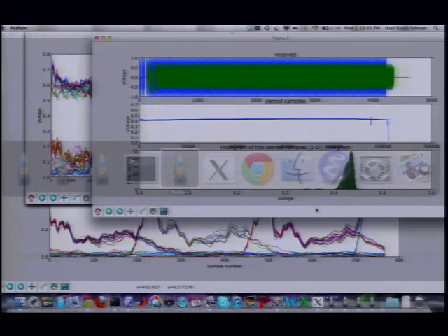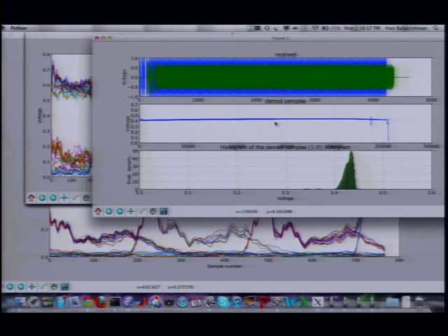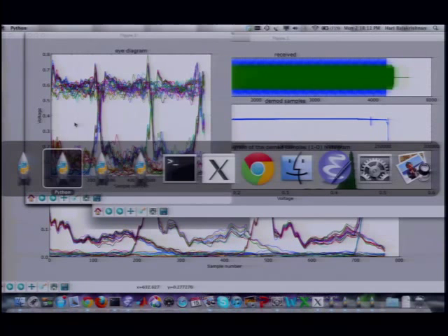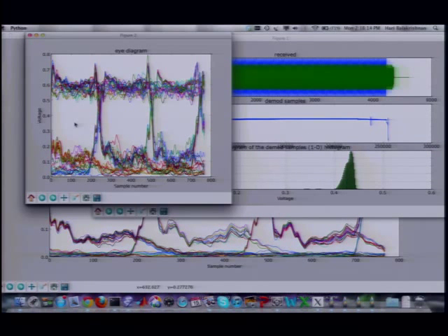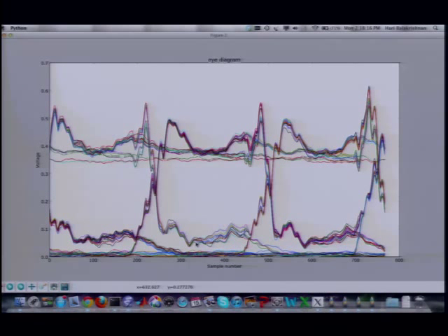We're seeing a superposition of many such 0 to 1 transitions, some 1 to 0 transitions, later 1 to 0 transitions, and so on. So we're really looking at a superposition of step responses staggered in time and going from 0 to 1 or 1 to 0. Do you think time invariance is maybe a good assumption for this channel? Plausible, right? Because the step that we get here looks a lot like the step we're getting here.